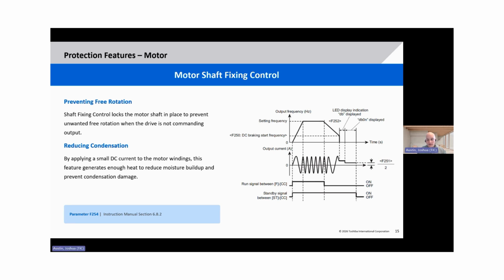The only caveat is if the drive loses power or experiences a fault, then the drive has to run the motor again and then stop before it will start applying that DC current again. So in critical applications, we would recommend a true motor space heater.